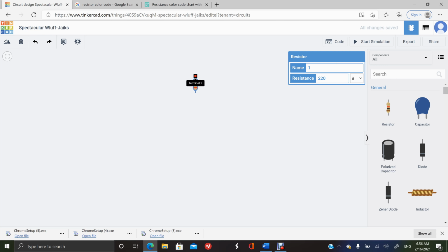They are color coded. So I have here on the resistor, let me just zoom so you can see it. So you have red, brown, and a gold. The first bar here, as we will see, is number 2, and the second color, which is the same red, is 2. So this represents the first digit. The second bar, the second digit, and the brown color, the third bar, that's the multiplier. So you multiply these two by 10 to the power 1. This value is 1. Gold is just the tolerance. It's how, for example, this one gold is 5% of the value. So it's like an interval plus or minus 5%, just to give you an accuracy of the resistor.